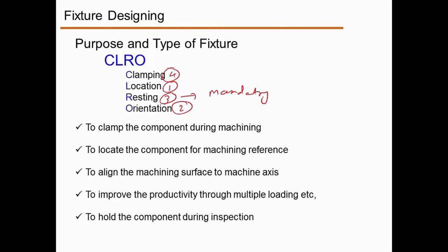As I said, the fixture is predominantly used in milling. For turning, fixtures are also available with the same principle, but predominantly people use it for milling, either on an HMC or a vertical machining center. Once you know how to locate the component and how to orient the component, because when you are writing the CNC program, the programming is done in a particular way.